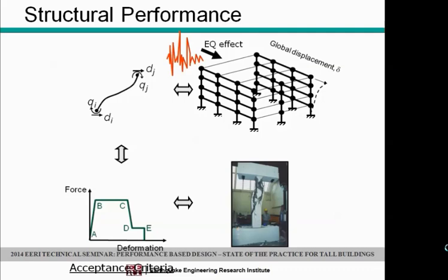But we use these hysteretic relationships that were developed from pseudostatic cyclic testing of elements. People developed backbone curves, shown in the lower left-hand corner there, to represent the hysteretic behavior of elements. We dump those relationships into our model, we subject them to an earthquake, and then depending on how much nonlinear deformation we get, we try and figure out how much damage is occurring in these elements based on laboratory data that's been gathered over the past 30 or 40 years or so.